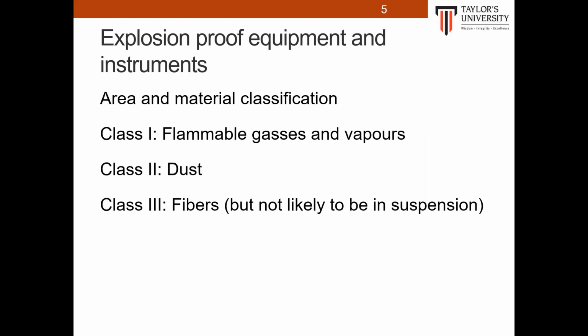XP stands for explosion proof, meaning flammable material, particularly vapors, might be present at certain times. The non-XP means that flammable materials are not present, even under abnormal conditions. For non-XP design areas, open flames, heated elements, and other sources of ignition may be present.